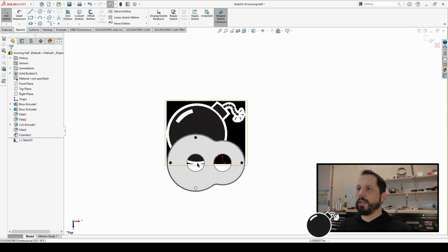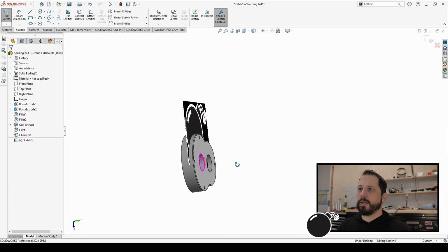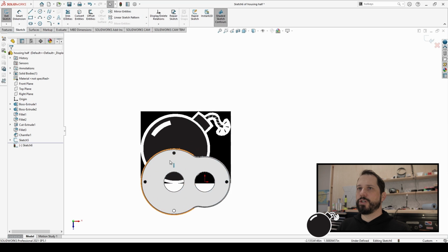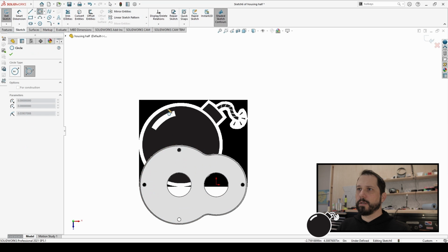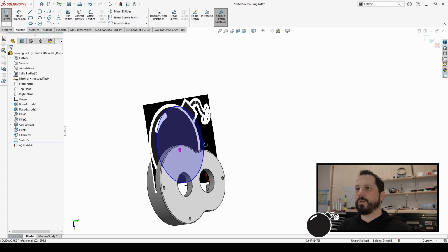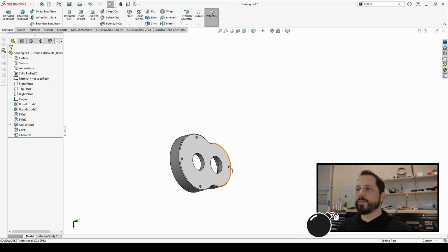And then you just hit OK, and then that is on that plane. It's just in a sketch. So you could name this sketch, reference picture. And then when you do your next sketch, you can then pick points on here. You're not actually picking points, but you can use it as a reference if you needed to have something match up.